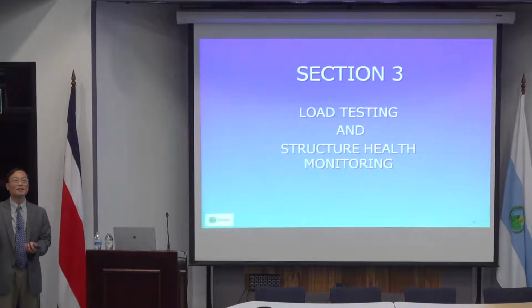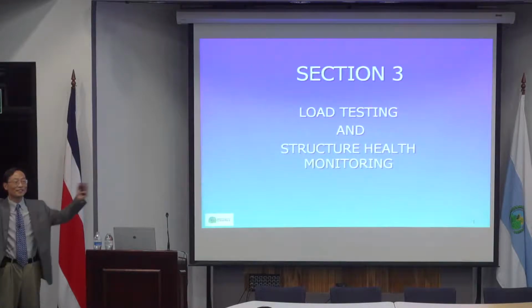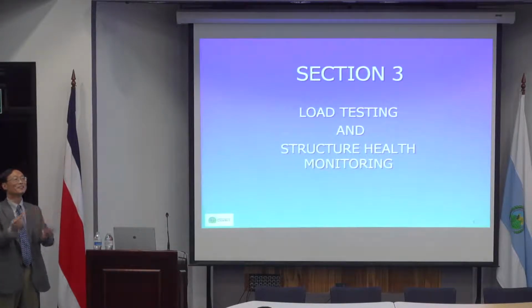And another thing about the model. The real tricky thing is what happens when you calculate capacity? Because if it's designed as non-composite, all you have is a net section. And if you add the concrete into this equation, then your capacity is actually much, much larger than before. And that may explain why there's no problem with the deck.